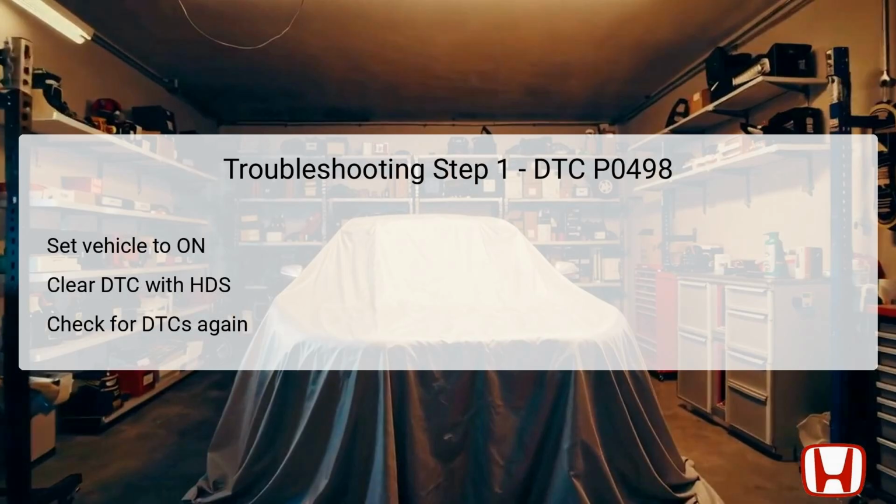Begin the troubleshooting process by turning the vehicle ignition to the on position without starting the engine. This action primes the vehicle's onboard systems and prepares them for diagnostics. Next, utilize the Honda Diagnostic System, HDS, to clear the DTCs present in the system. Clearing the codes is critical to establish a baseline for further diagnostics.